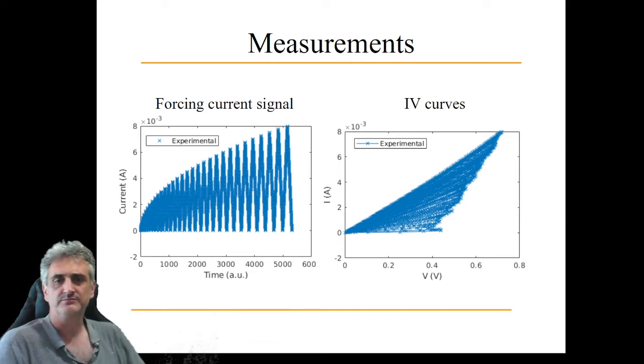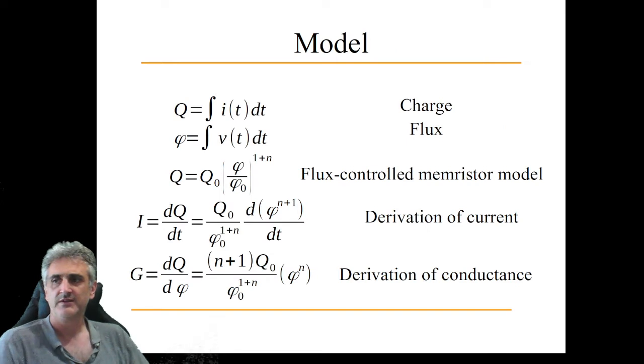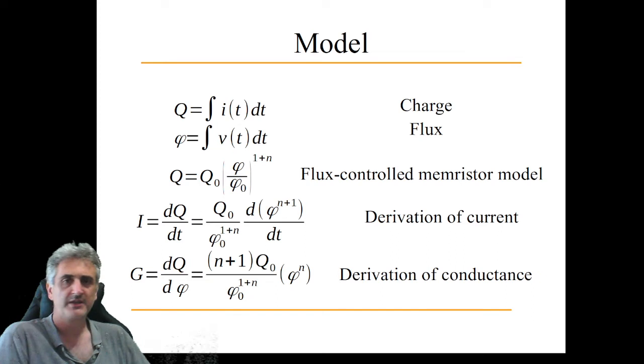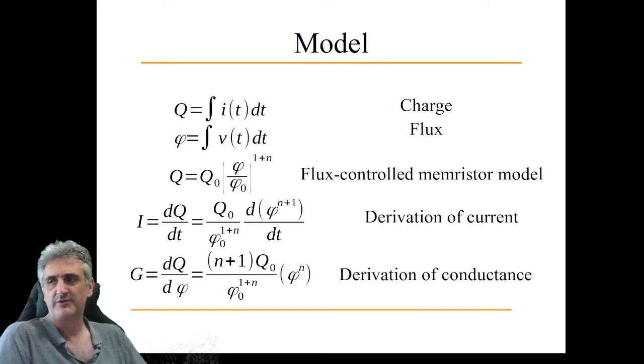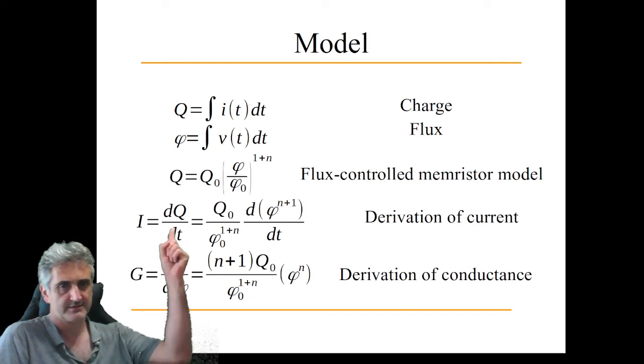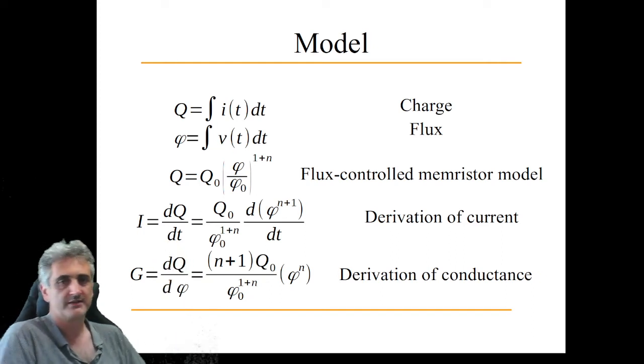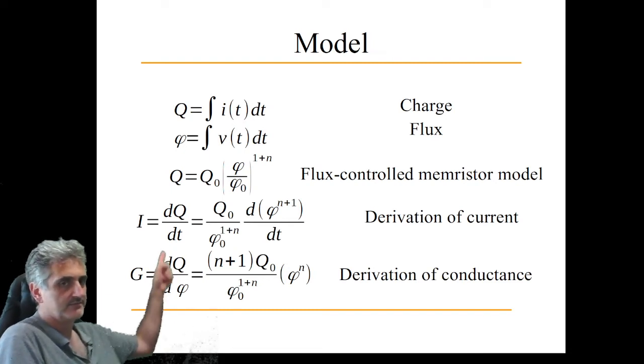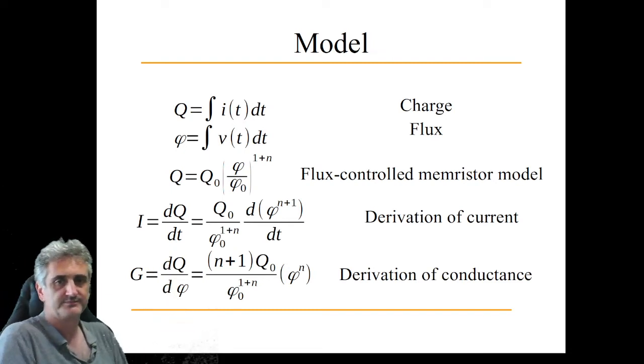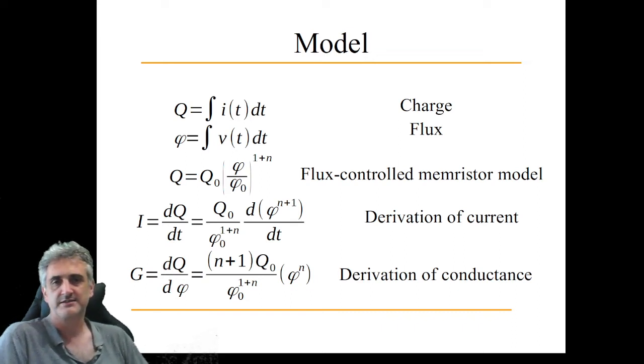So in order to model that, we used the typical way to model using charge and flux. We first define the charge as the integral of the current, the flux as the integral of the voltage, and we define our model as just a simple power relation between the flux and the charge. Using this simple relation, we can develop a relation for the current and also a relation for the conductance. But the model is just this power relation.